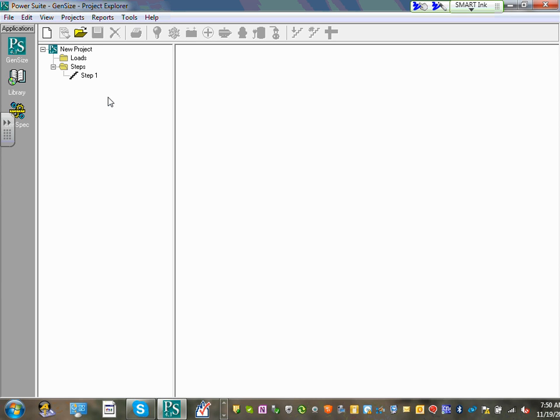Starting load versus running load. So your job is to minimize, try to start them in gradually, in steps. What's the most important thing? Starting. 10 seconds, start the second thing. 10 seconds, start the third one. And the fourth, and the fifth.